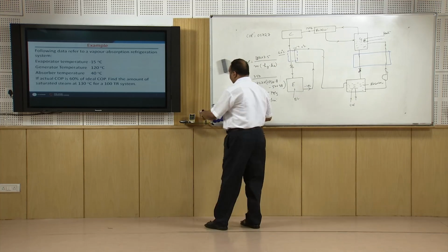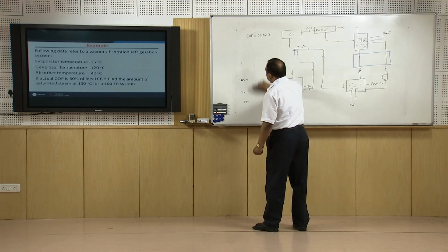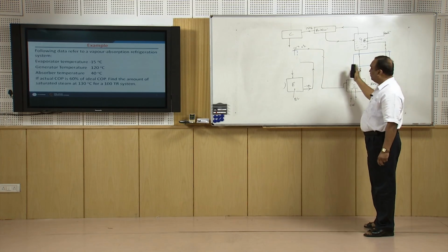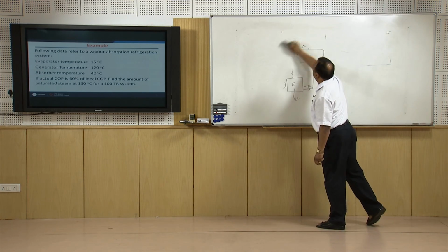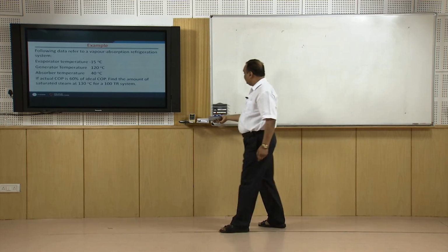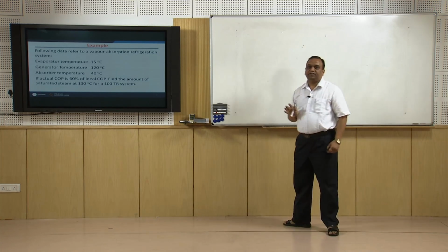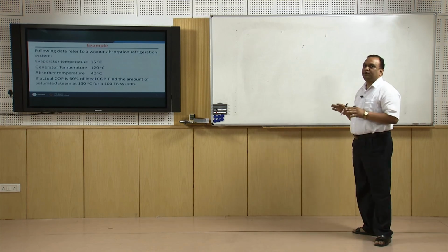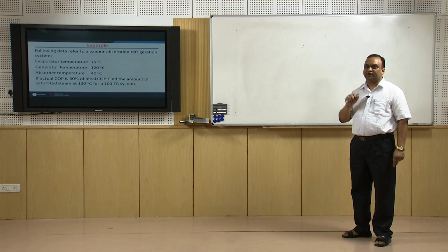Now after this there is another combination of absorber and refrigerant, that is water and lithium bromide. In the water ammonia system, water is absorbent, ammonia is refrigerant. Now here in the lithium bromide type of system, the water is refrigerant and lithium bromide is absorbent. This lithium bromide water system works on a very low pressure, and in different books you will find different type of arrangements. It has 4 drum arrangement, 1 drum arrangement, 2 drum arrangement is also there.